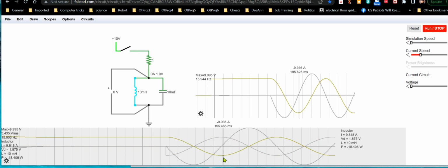So, the current of the inductor, of course, falls off as it discharges, until finally it reaches 0 at peak voltage. And again, since we got a peak voltage, that means the capacitor is fully charged, and the capacitor's current is 0, which is what you normally expect for a charging capacitor. Expect its current to fall while its voltage rises.